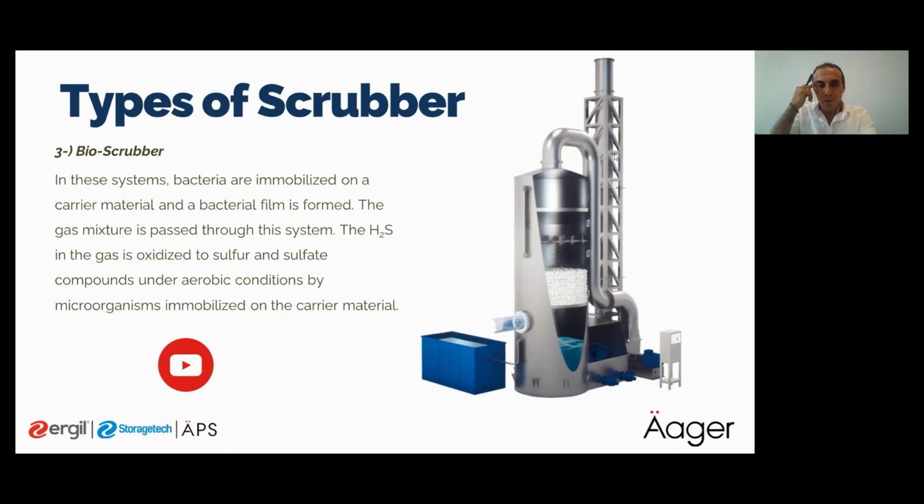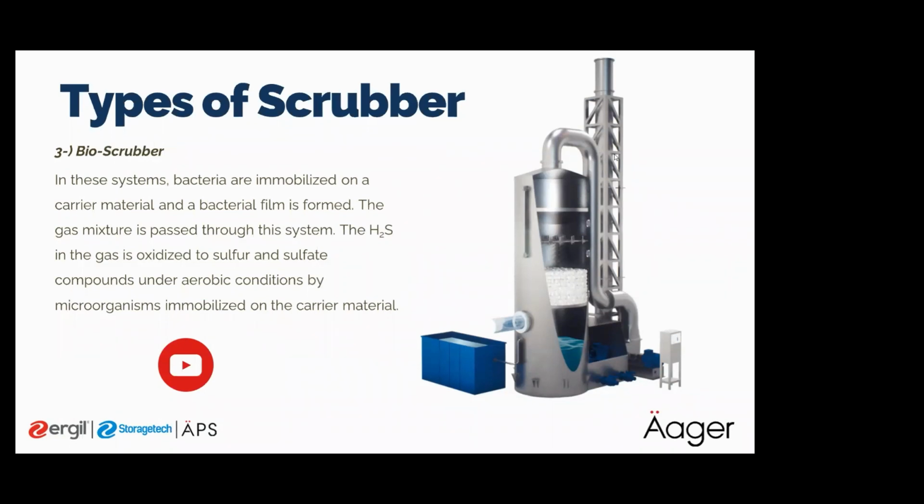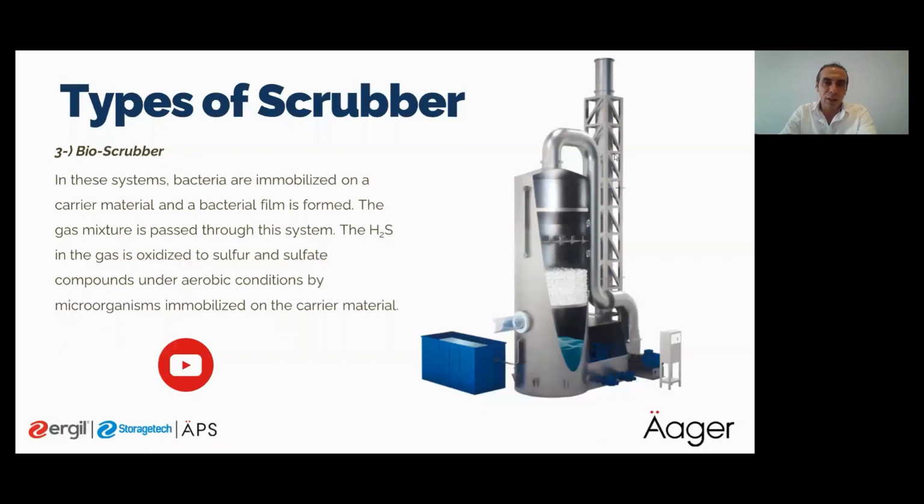Okay. Actually, scrubbers cannot be used as a heat recovery unit. You can do it before the scrubber, because you have to reduce the temperature of the waste gas before the scrubber. Some of our clients use a heat exchanger before the scrubber and reduce the gas temperature.